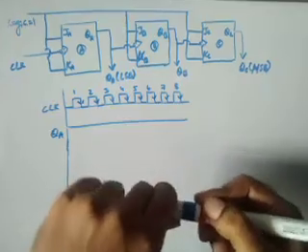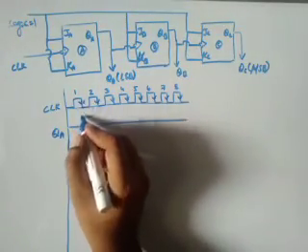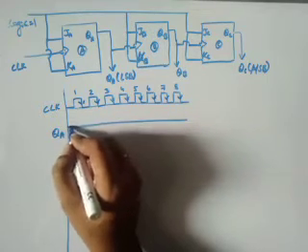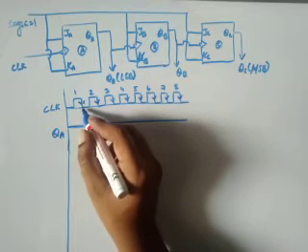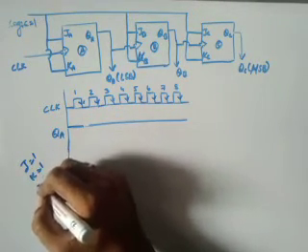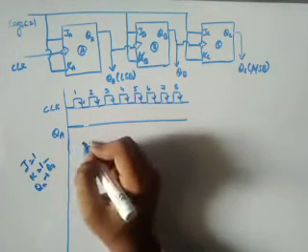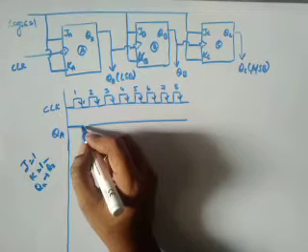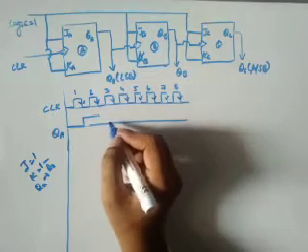So up to a negative edge point, up to here, you are going to have a previous state of 0. Whenever it has a negative pulse, it sees the inputs J equal to 1 and K equal to 1. So Qn becomes Qn complement. Now what is the value of Qn here? Qn is 0 and its complement is 1, so it will hold that up to the next negative edge.